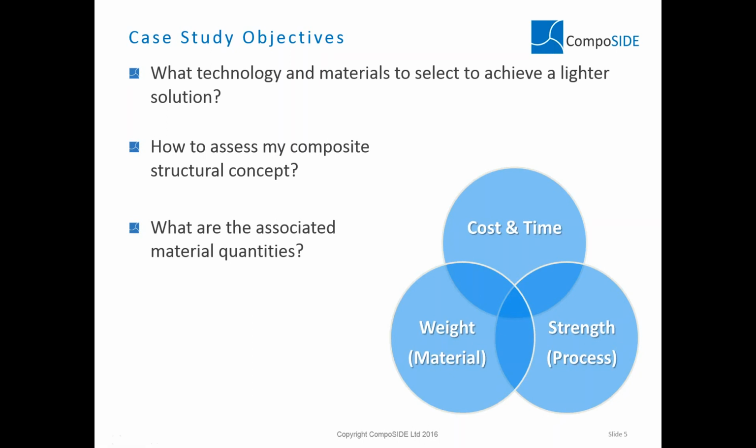One approach that is quite widely used in the market is to take the total material weight of a structure and ask for the pricing of similar quantities of carbon or glass, otherwise known as the black metal approach. The outcome is almost certainly not favourable to composites, and is also wrong for the vast majority of cases. The first questions are generally related to the business case. It needs to make sense from a business and a product point of view. How much weight can I save? How much stronger or stiffer will the resulting structure be? And the obvious, how much more is it going to cost?